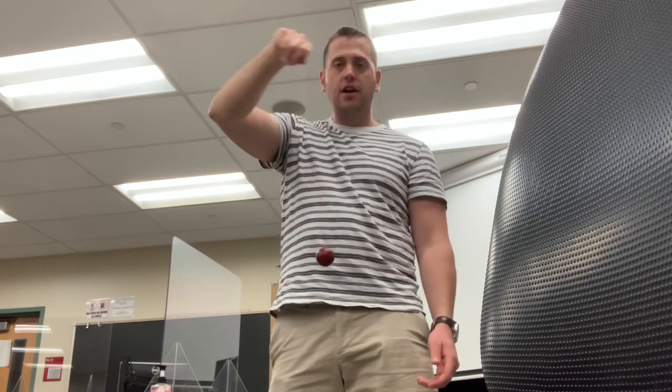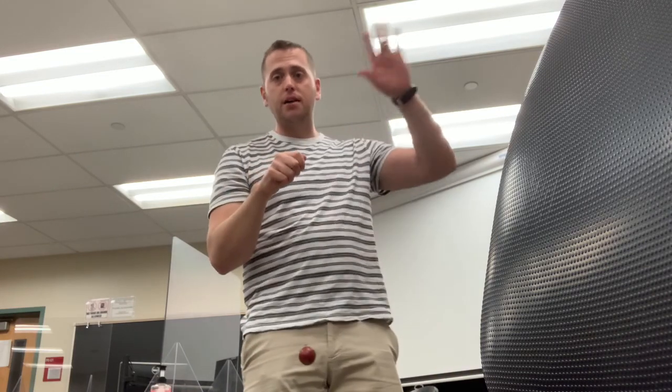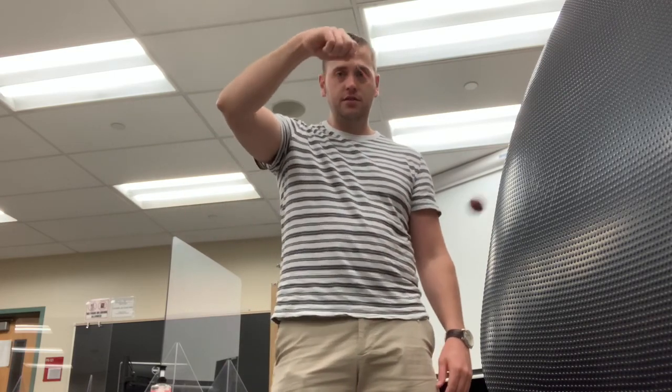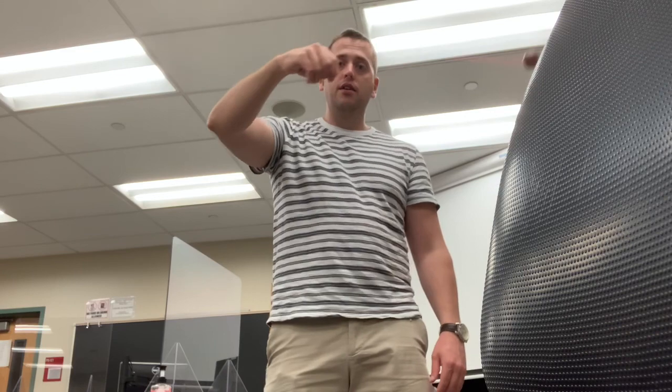So for example, if I shake it back and forth very quickly like this, the pendulum mass is not really responding that much to what I'm doing. Okay, so in other words, the driving frequency is way above the resonant frequency, and it's not really responding to that. So if I decrease the frequency of my driving force, and shake it more like this, now I'm getting a very large oscillation. So this is what resonance is all about. If I drive the system at the right frequency, I can get a very large oscillation.